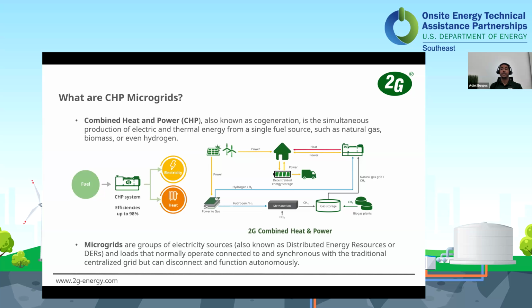In the industry, it can mean thousands to, in some pharmaceutical cases, maybe even millions of dollars if they lose conditions on clean rooms and have to dispose of product, plus the operational costs. Having those systems online can help you improve the power quality, and a well-designed, resilient system can even help you ride through swells and dips on the grid itself.